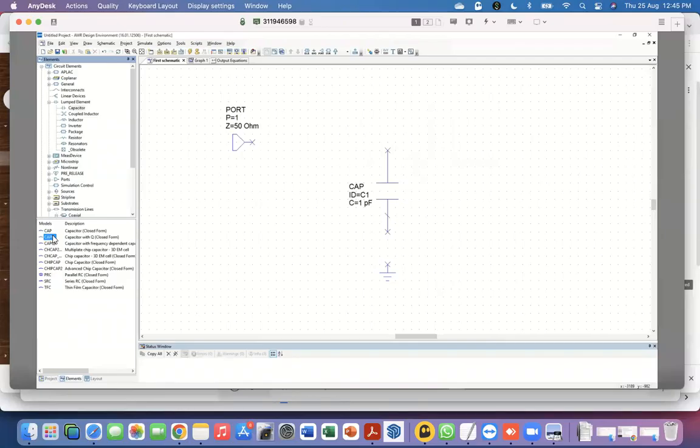So that allows you to be a little bit more realistic when you're using, let's say, a particular brand of capacitor. I haven't used it in a long time, but you can actually import the data from some commercial model. By looking at the model number, you can import that data here and it will simulate it according to that. So that can be useful to really know that, okay, you have created an ideal circuit.